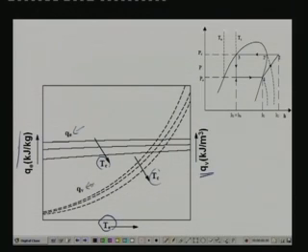From this graph you can easily see that as you increase the evaporator temperature for a given condenser temperature, there is a marginal increase in specific refrigeration effect. And the specific refrigeration effect also increases as condensing temperature decreases. That means QE increases as TE increases and TC decreases. But as I said, this effect is not very large, it is marginal.